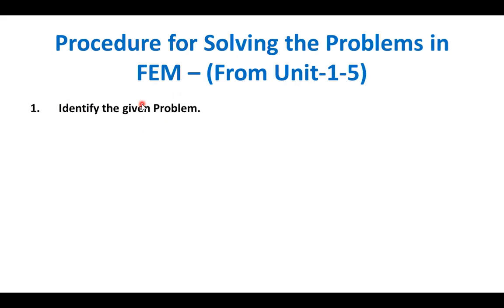So the first step is to identify the given problem, whether it is related to heat transfer, dynamic analysis, or structural analysis. If it is structural analysis, you should use the appropriate element for solving the given problem. So the first and foremost step is to identify the given problem.